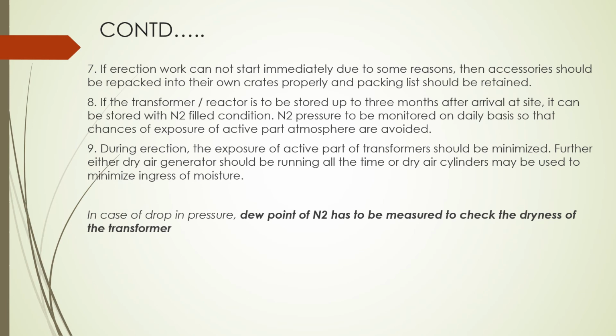If erection work cannot start immediately due to some reasons, the accessories should be repacked into their own crates properly and packing list should be retained. If the transformer is to be stored up to 3 months after arrival at site, it can be stored in nitrogen filled condition. Nitrogen pressure to be monitored on daily basis so that chances of exposure of active part to the atmosphere are avoided.